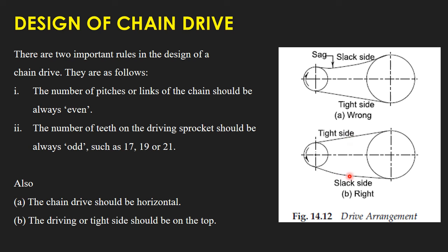If you observe your motorcycle, slack usually takes place at the bottom portion of the chain drive, and that's why when it hits the housing, you hear an unusual sound. Immediately, if sagging or slack is found, you have to pre-tension the chain so that such noise and sagging can be eliminated.